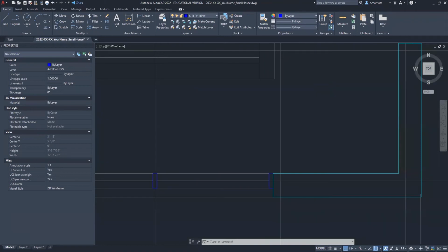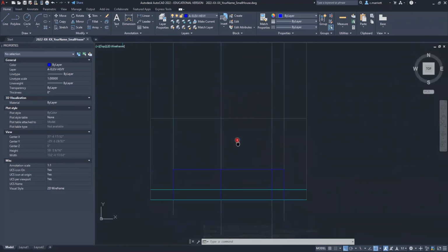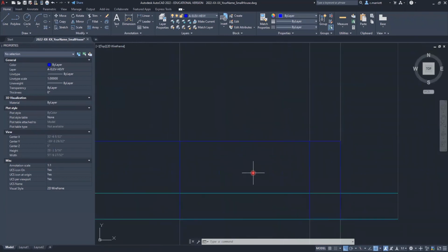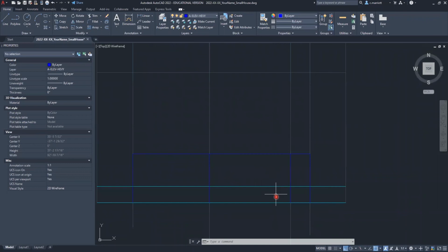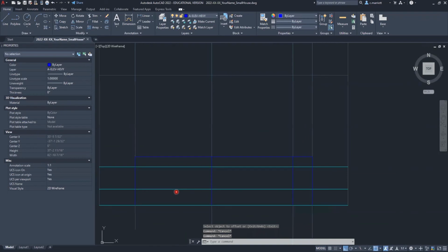And if they are in plan view, they're very likely going to be the same dimension at the top and bottom of the window. So for a door, if the door is 7 feet, then you add 1.5 inches. I could type in offset 7 feet 1.5, or I could just do the math and figure 85.5. Okay, so this is going to be the top of the window line. And if I had a door, it would be the top of the door line.